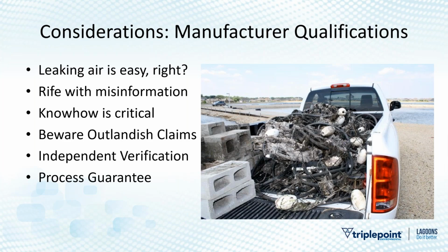If a manufacturer is coming to you and they only work in wastewater lagoons, and they're saying, "I have the best thing in the world, no one else can do it this well," the next question would be, well, why isn't every activated sludge plant in the country using this technology? Why are you only selling to lagoons? Oftentimes, there are some chinks in the armor, and you just have to figure out what smoke and mirrors are being played. There are a lot of games that can be played, and independent verifications are a really good tool to help get through that.